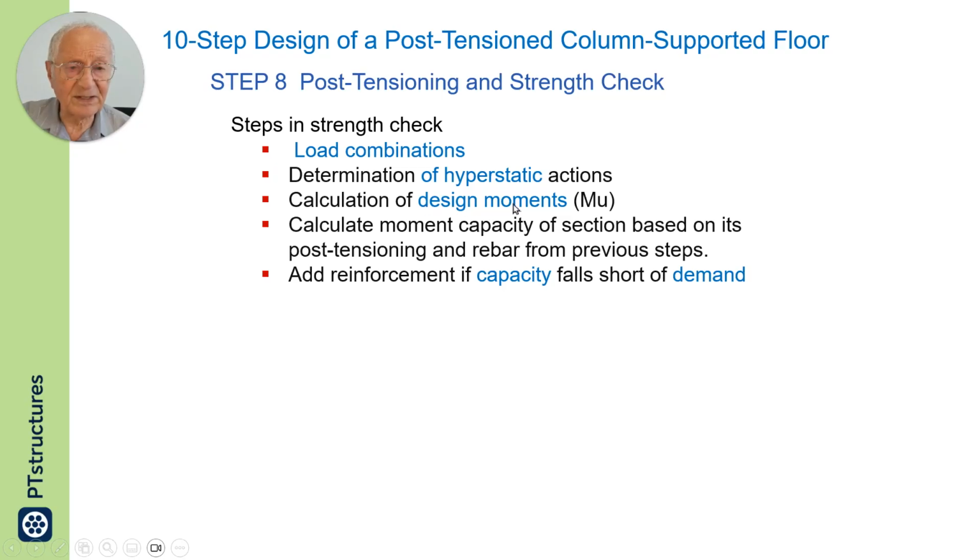After we calculate the design moment, rather than design the section to resist the demand, we look at the section and we observe that it has post-tensioning tendon in it. It has minimum rebar in it from serviceability.